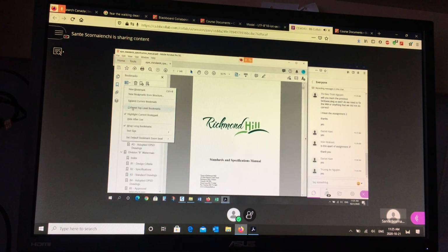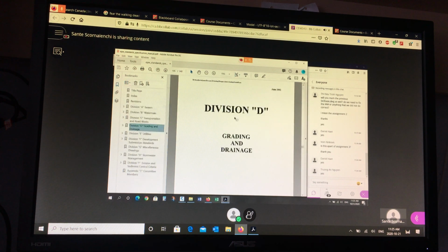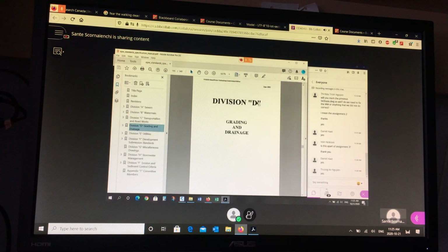collapse all these. If I go to not sewers, not water main, not transportation, but grading. So here's the grading division. This is about lot grading. It's worth reading this entire section just to prepare for next semester. There's a similar one in the Town of Milton standards that we're going to use next year. So we want to look at minimum and maximum slope. We want to look at maximum transition sloping and so on.